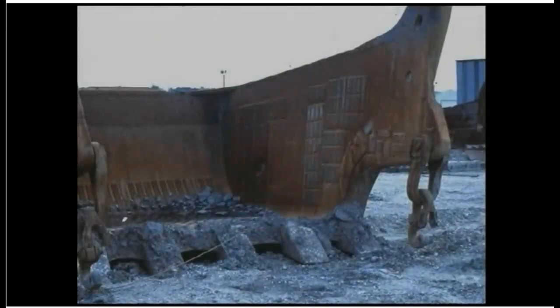Gas metal arc welding is a versatile process used on everything from small parts to heavy fabrications. It can also be used for surfacing and build-up operations. Gas metal arc welding uses the intense heat of an electric arc to melt a continuous electrode wire and base metal. The molten filler metal transfers across the arc to the work, where it fuses with the base metal to